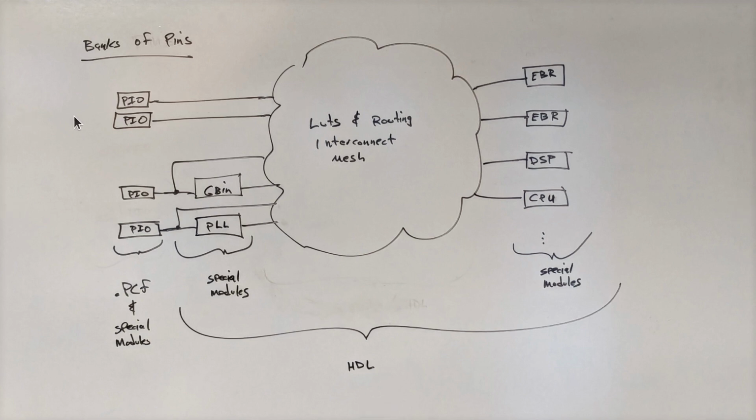What we will have achieved in doing so is we'll take a look at what goes inside the pin configuration file, because we're going to have to configure 2 pins in order for this to work. We're going to have to compile a program that has 1 line of code in it that says the output equals the value from the input. We'll have to run all the tools, and then we'll have to program the FPGA and get all that stuff to work. This is really the hello world program of an FPGA.